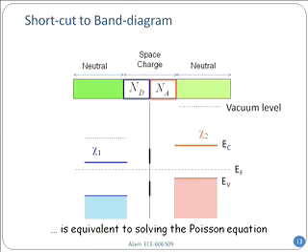Okay, now the next step is making the vacuum level continuous. So you see on the top side, I have this red curved line and the blue line. It doesn't have to be exact. I just make the vacuum level from one side go to the other side without any discontinuity in it. It could be completely wrong, but just draw a line which will go from one side to the other. Okay. Now the next step is this. Let's focus on the left-hand side of the conduction band, for the donor side. Whatever vacuum level line you have drawn, you just copy and paste like this.